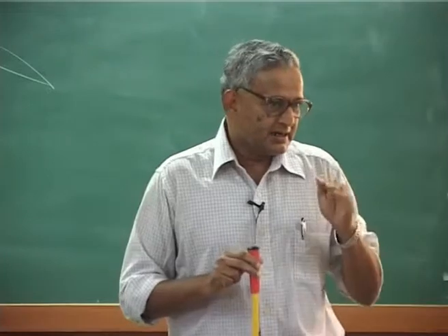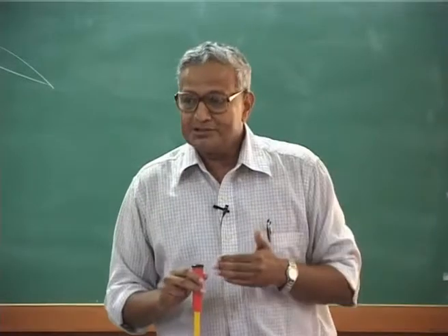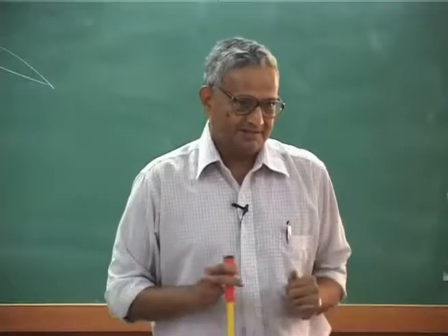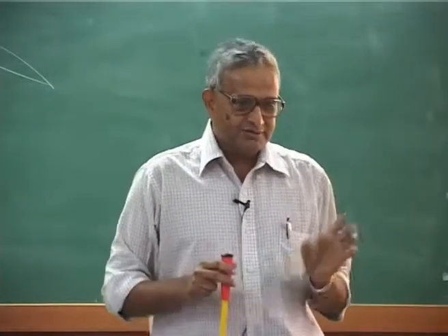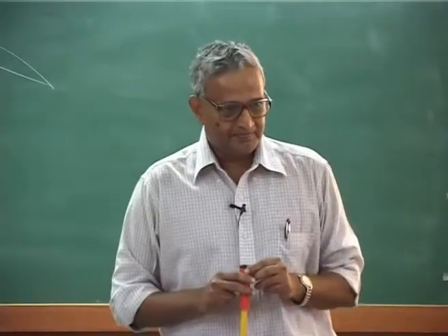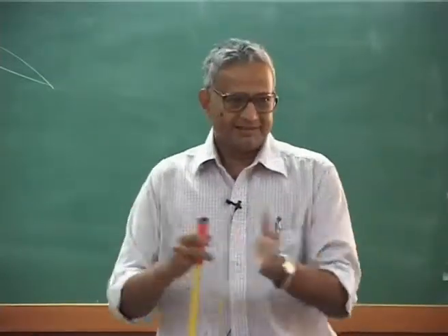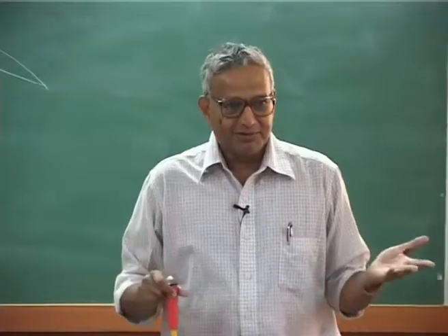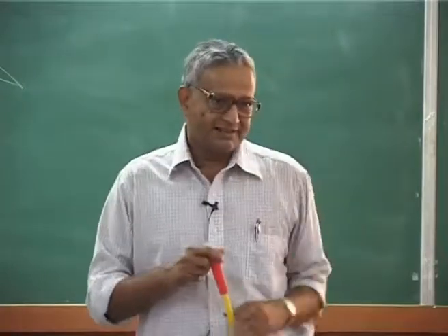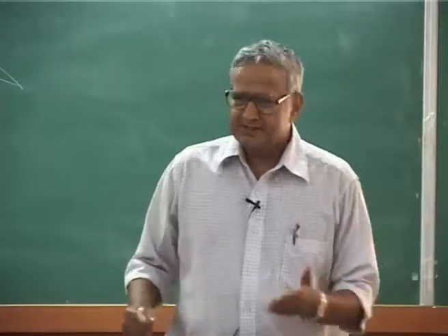But he did not take into account the velocity due to the inflow or the induced velocity. He just took the propeller forward velocity and then the omega r, and when he calculated the thrust, the power, etc., it was not matching with the experiment, because please understand, lot of propeller experiments were conducted earlier for power and thrust, and he found that they were not matching,